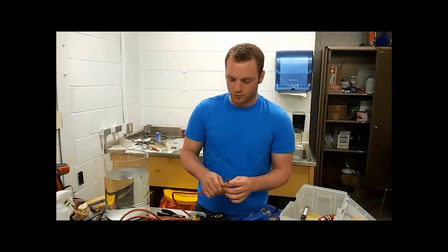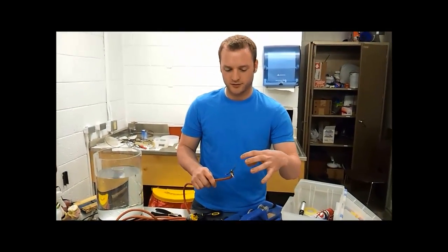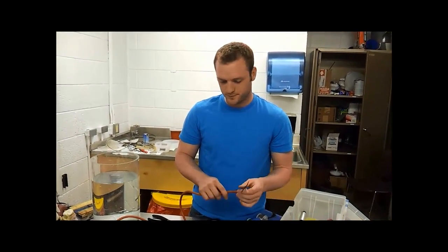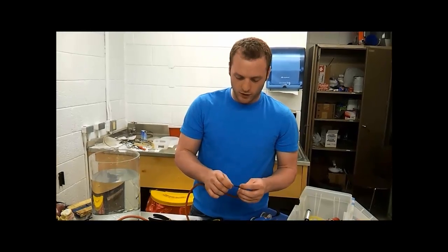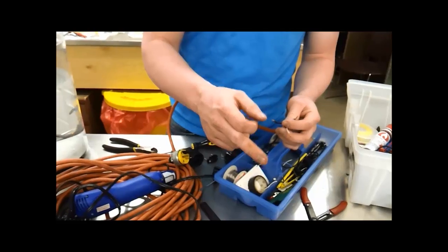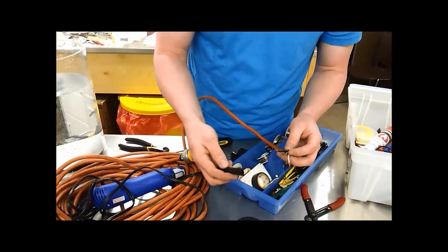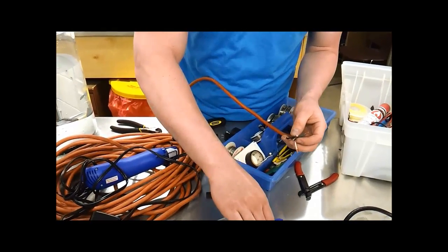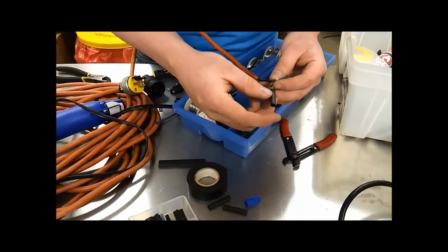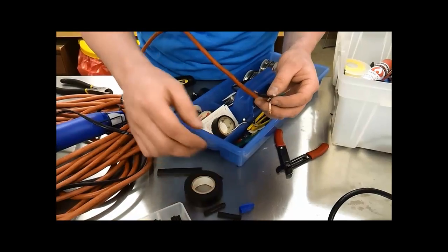Alright, so next step is we're going to make this cable longer by connecting this waterproof cable to the cable of the sump pump. To do that, we're going to solder these 3 connections onto the 3 connections of that wire, and it requires a little bit of planning. Because after we solder them, we're going to heat shrink them. So each one of these is going to be shrunk onto the end of that, to provide a really good connection.